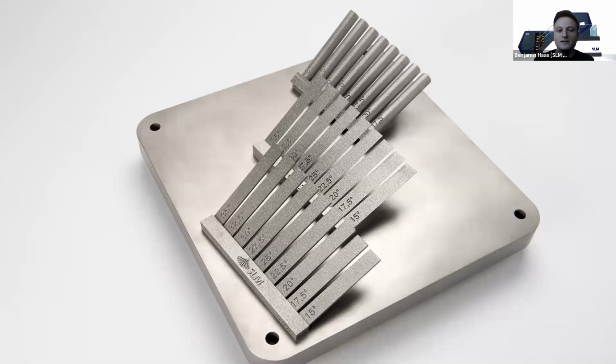So the main reasons for supports are to sort of carry out the heat and the thermal energy that we put into the powder bed out of the part, to allow it to cool down, and therefore prevent internal stresses, and also to keep the part in place. Because some materials, especially titanium alloys, are quite prone to distortion, and those supports just keep those parts in place and prevent them from warping up.